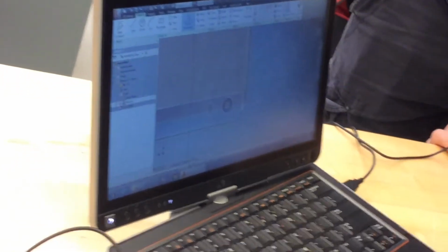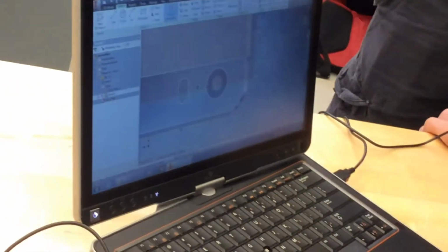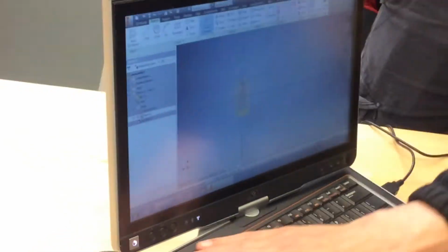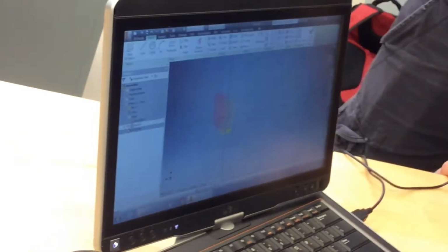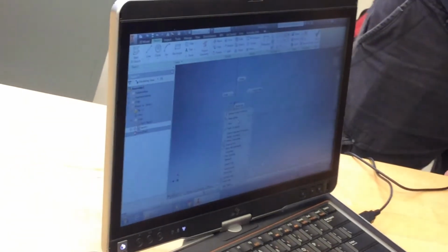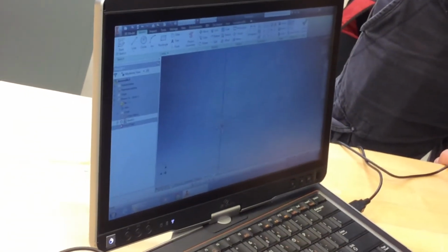one step. So then I'm just going to project that geometry as well. Just the camera and the flash and the sensor, okay? Then I'm going to hit escape. And I'm going to use all these as references. So I'm going to highlight this whole thing, right click, construction. So now I have all construction lines as a reference, okay?